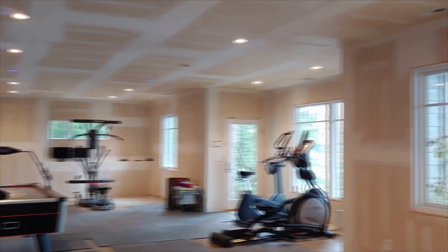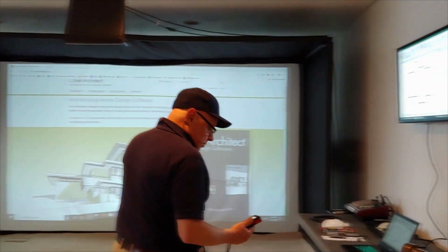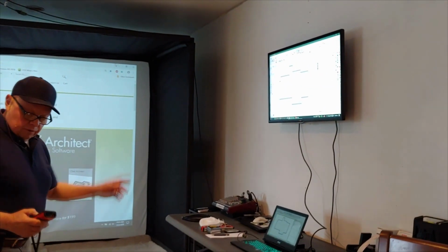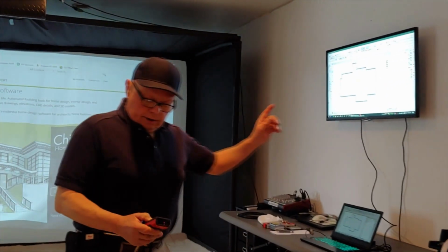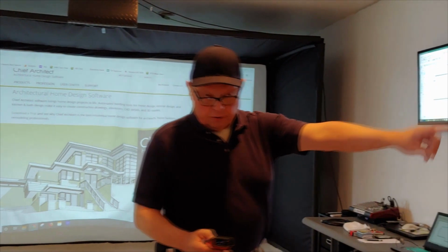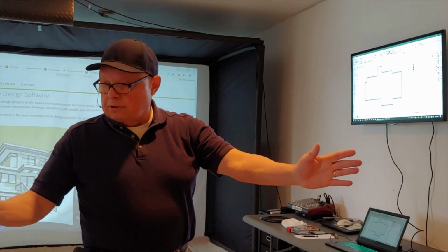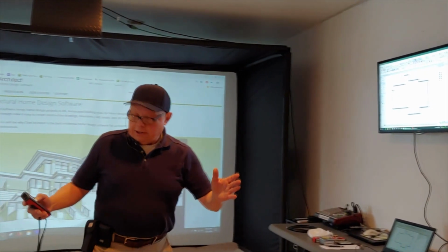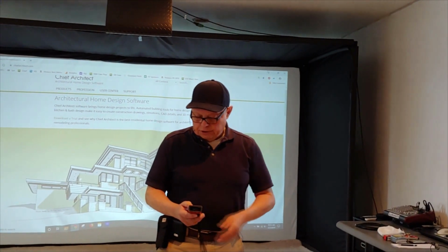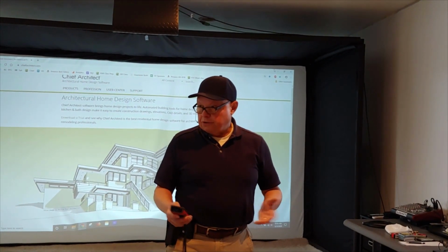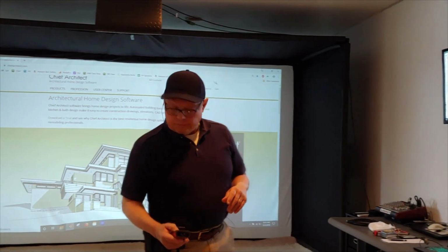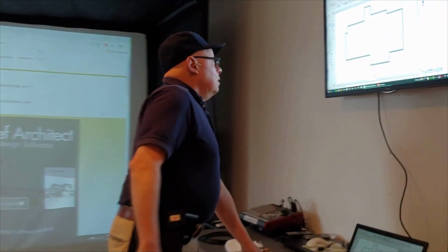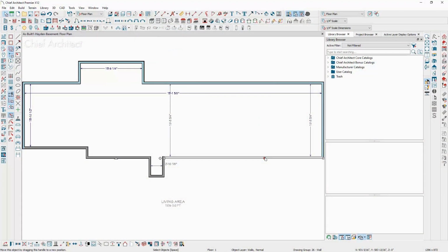All right, so we've got 4 dimensions here. And at this point, I'm just going to go back and start putting some things in. Now, I've also noticed that I'm going from 18.3½, 18.3 and 9/16, 18.3 and 11/16. So the room's widening out. Okay, so it's only about 1/4 of an inch out. In a case like this, I might use the average. Take the 9/16. It's just not that far out that it's worth noting. Okay, so this dimension here is going to 18.3 and 9/16, and I'm going to move this wall to do it.